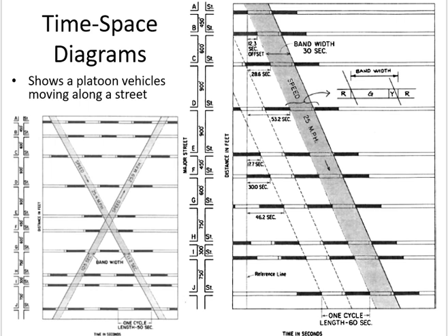At each band, you can see the signal timing. This is when the signal is red, this is when it is green, then this is when it is red again, and so on and so forth. So you can see at each band when the signal becomes green and red. Clear? Now, how do I do the coordination? First of all, you draw this diagram. Time, distance, and on the distance axis, you make these bands for each intersection according to their distance. Clear?